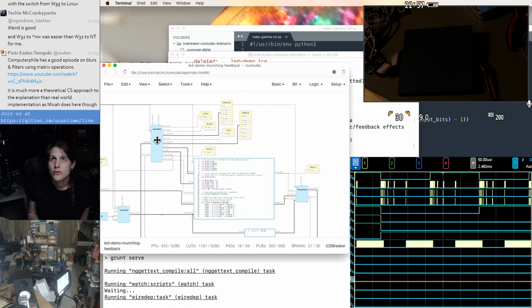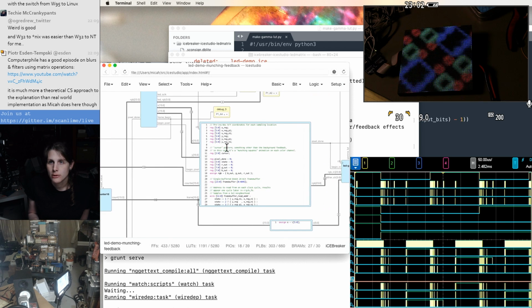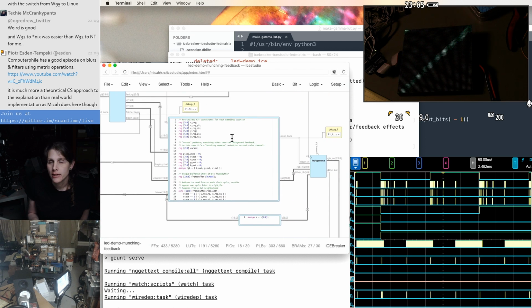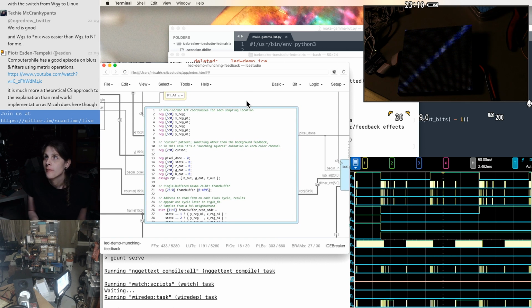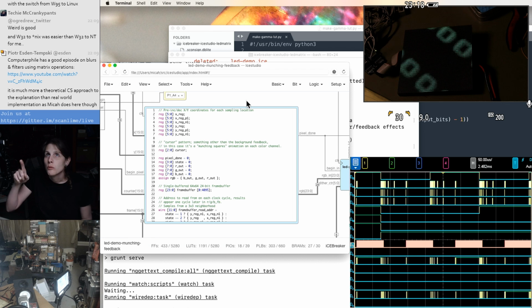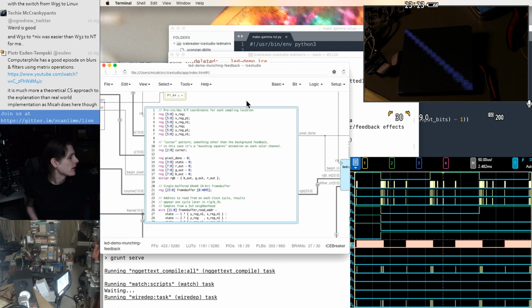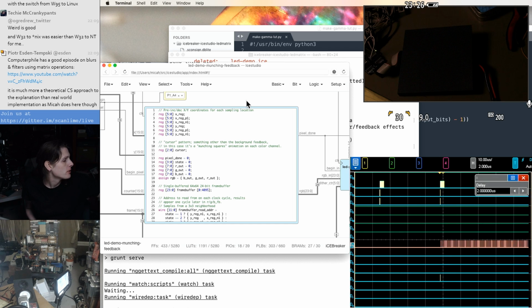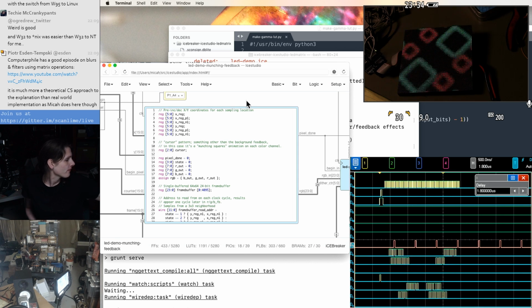So we've got the LED driver from the last several streams, input counters, and then this is sort of our shader logic. So this is filling a buffer with pixels once per line, and then just kind of hanging out until the next line starts. That trace D7 on the scope, this one in red now, kind of pink, I guess. The wiggles on D7, each of those pulses are a pixel finishing. And then when it goes quiet in between rows, that's just where we have no more pixels to do, and we're still actually presenting the pixels we've seen so far. Oh, that's a nice view.